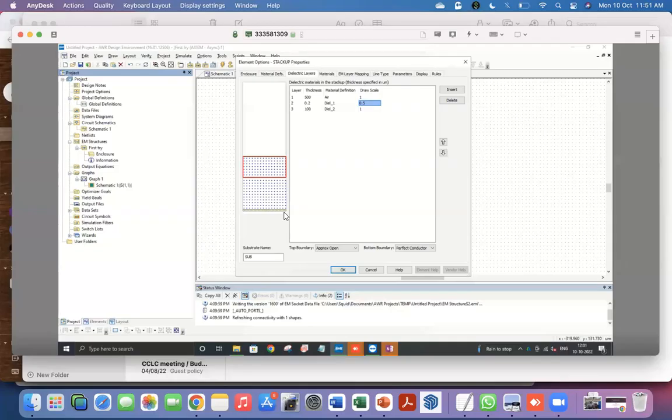Again, we don't know the details of the actual solver, but essentially this means that you don't have to solve Maxwell's equations in 3 dimensions. You're solving them in 2 dimensions with some approximations, and these definitions allow you to take into account the effect of the dielectric. So it's a simplification of the system.